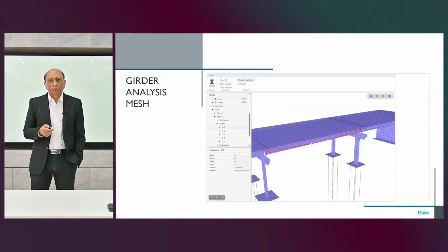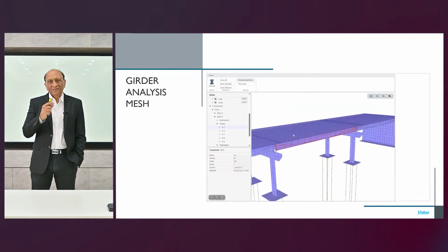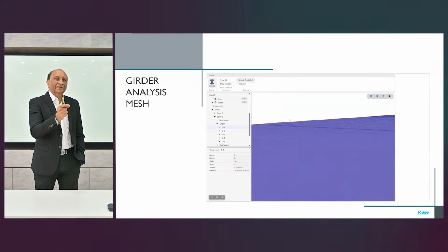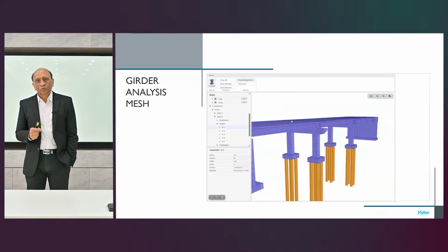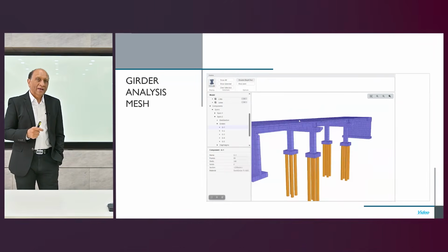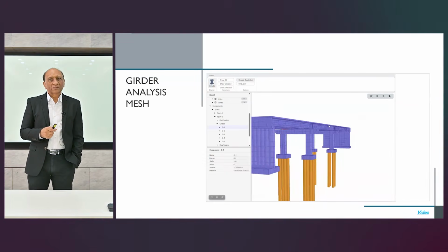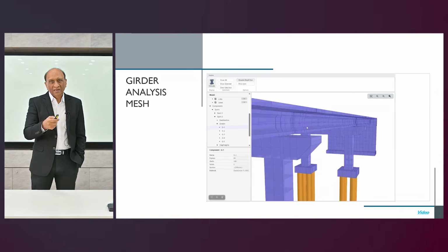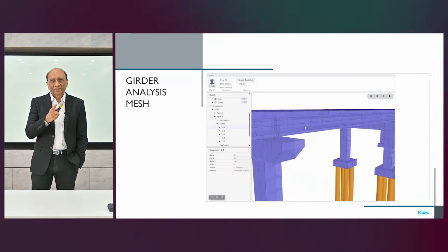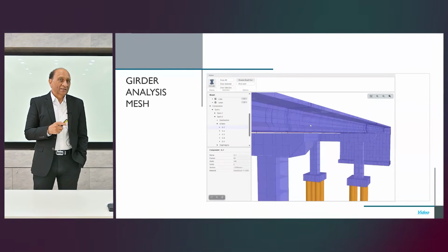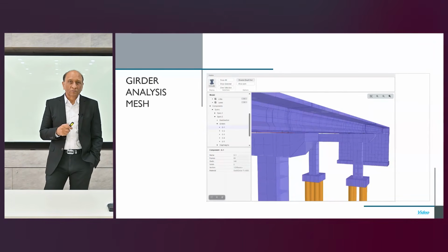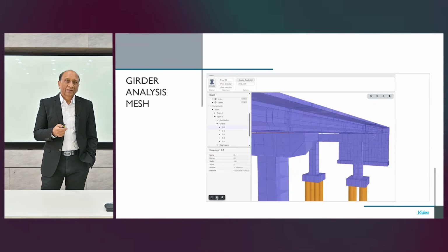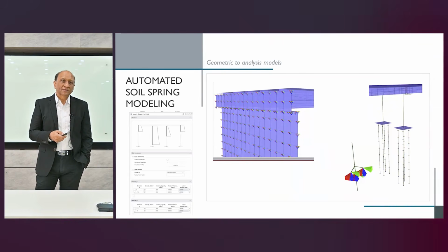If you go closer, you can see how the girder is correctly modeled, correctly attached to the bearing, and the bearing is correctly attached to the substructure. So when you do the analysis, you will not be losing any of the behavior in this model. And if you extrude that shell element, you get the same physical model back, including the variation in the girder section. It looks almost exactly the same as we started with. This kind of complete modeling is very helpful in capturing the response.